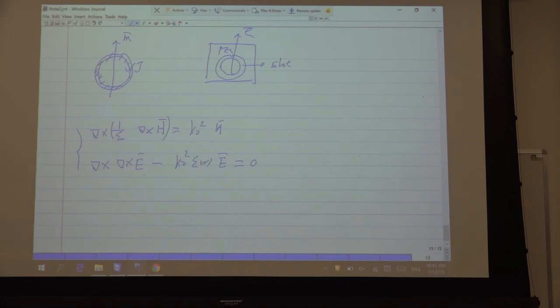From this eigenequation, we know that it has eigenmodes Em, Hm. For any excitation solution, I mean del cross del cross E minus k0 squared epsilon_r E equals i omega mu J, this is the excitation solution.